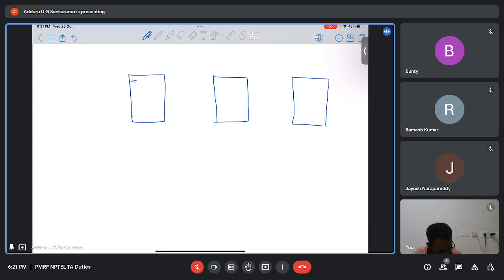Let us say I'm using JK flip-flops, with J and K at 1, then only it will be in toggle mode. So J and K are connected to ones. Now for the first flip-flop, let us say a negative edge triggered flip-flop.